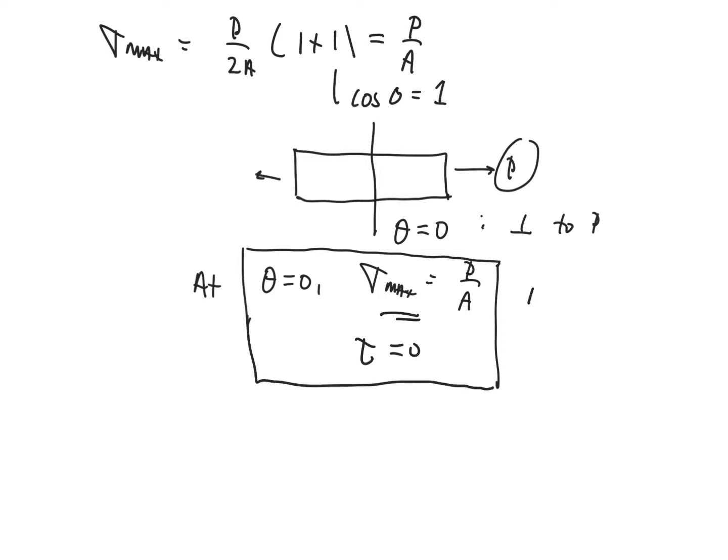Now that I do want you to memorize. That's important. So the largest stress that you can get in an axially loaded bar is going to be P over A. And so that's nice for us because it tells us what a critical value is going to be. So things kind of condense to the simplest possible state in that case.